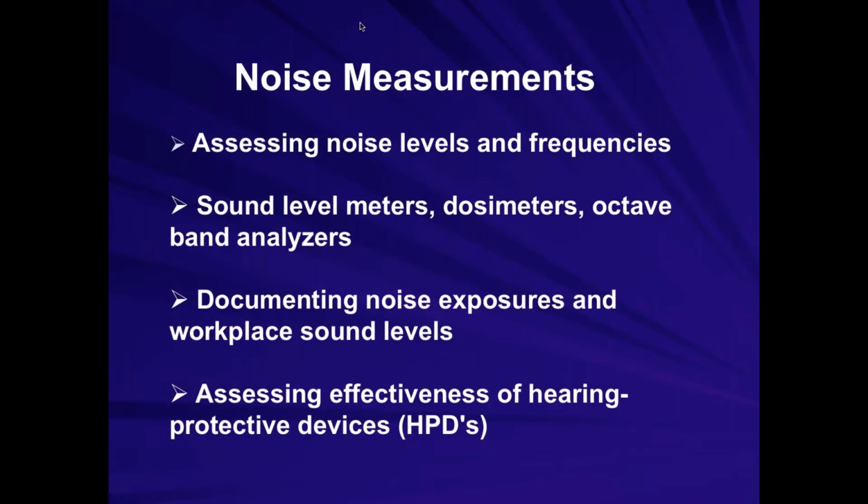We're going to be using a couple of different kinds of tools. One of these tools, which Mike has right here, is a sound level meter. Basically, it's just a device with a microphone on the end of it that will measure the amount of noise that's reaching the microphone and display it on a little LCD display. Anybody want to hazard a guess what the units are on this device that are measuring sound? Decibels. Decibels, exactly.